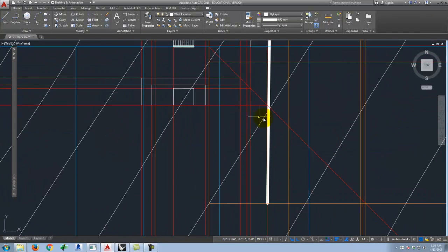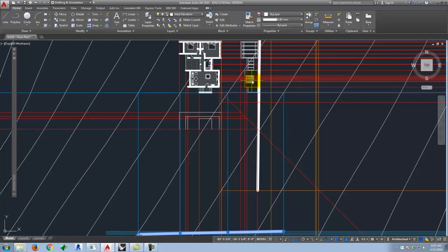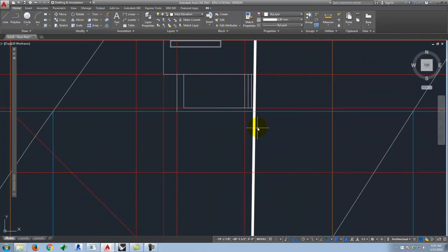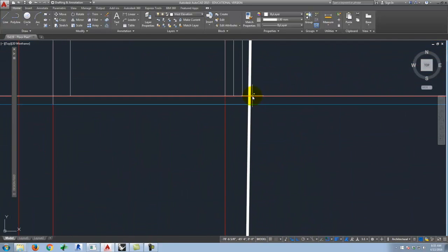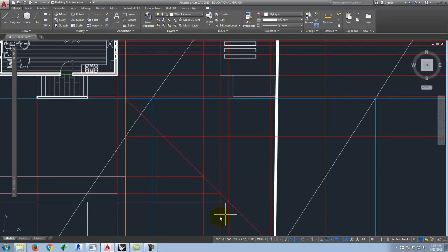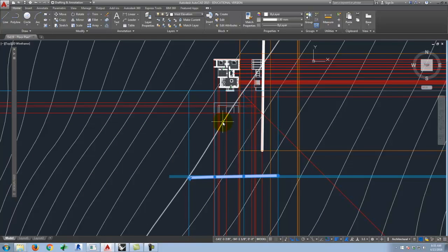Now, it does matter, however, where this elevation falls. And I have to line it up and wrap it around the same 45-degree line that I did before. So I need to find out on the edge or corner of the building right there, and pull that line around so that my topo ends up in the same place in elevation.